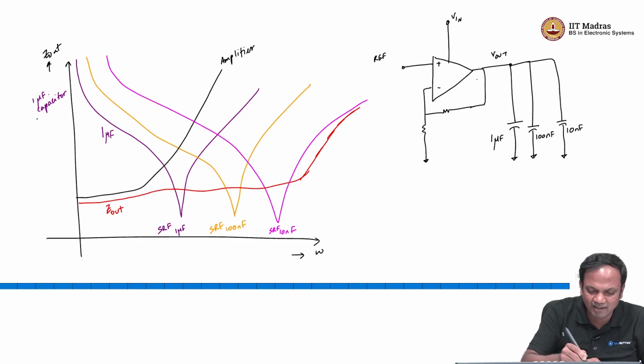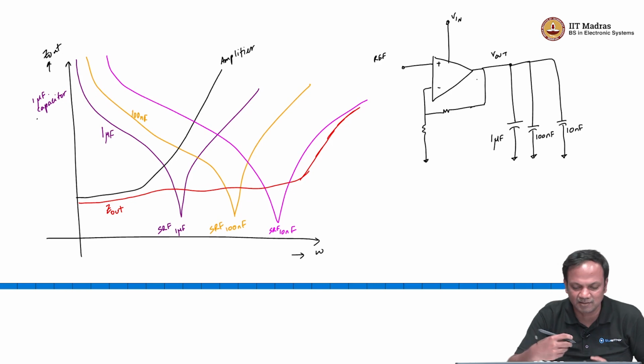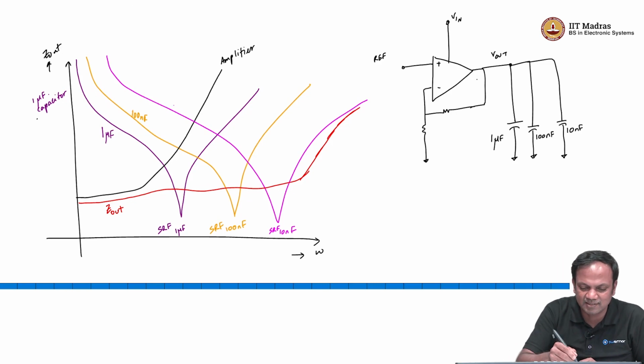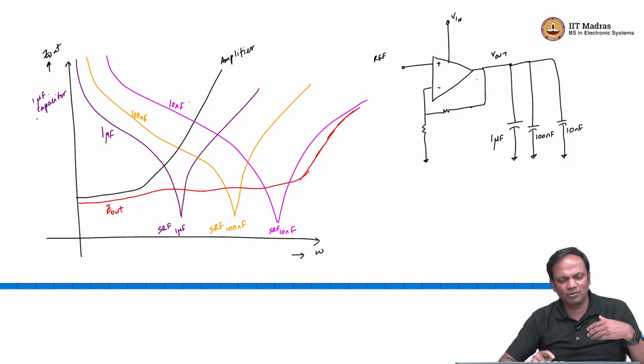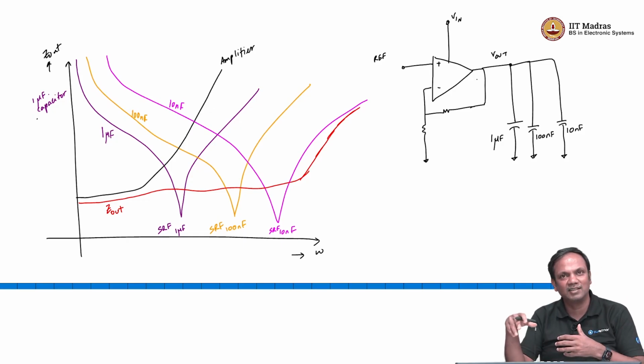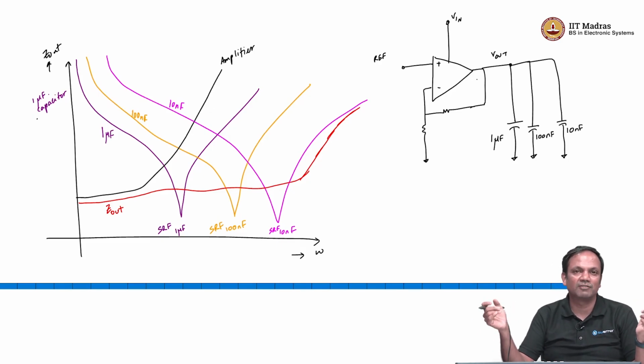And then the 100 nanofarad capacitor says okay, we have hit the self resonant frequency of the 1 microfarad, but I am still behaving like a capacitor, maybe I can take some of the load. And then once it hits its self resonant frequency, the 10 nanofarad capacitor can do the same, where it says okay, 100 nanofarad capacitor self resonant frequency is also hit, but I am still functioning as a capacitor. So, we can maintain a lower impedance over a wider frequency band.